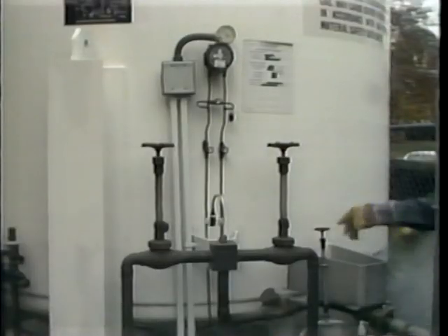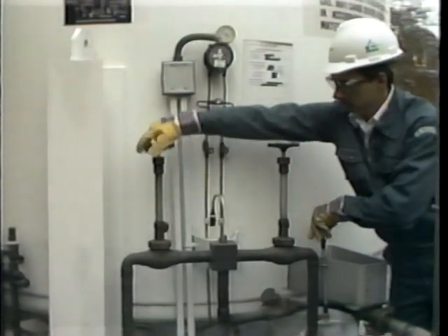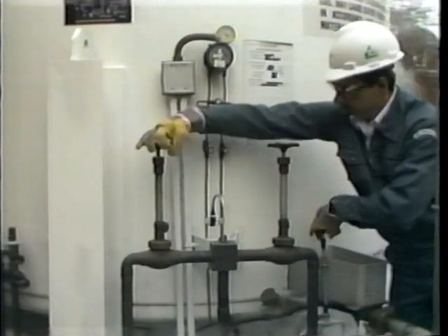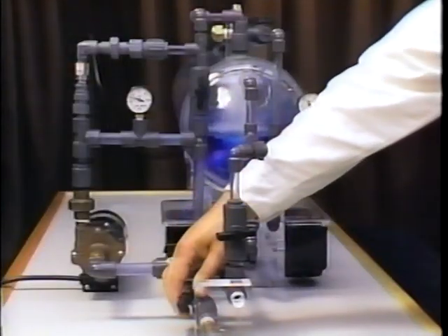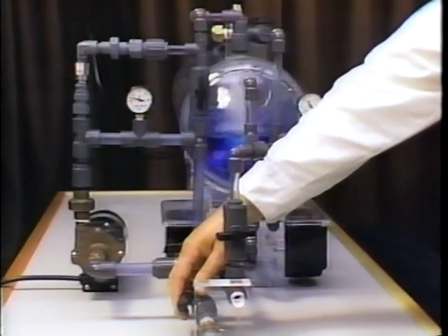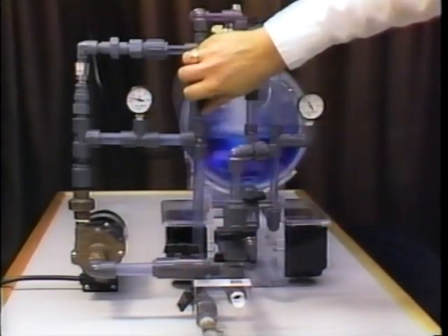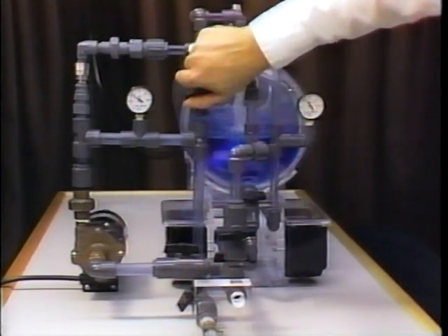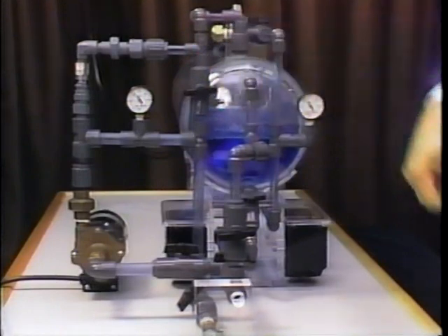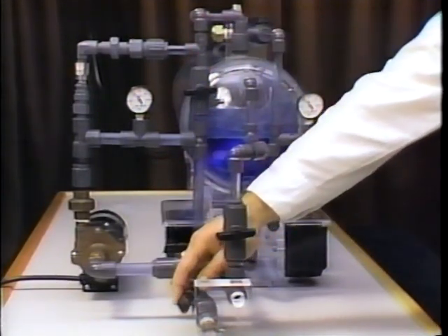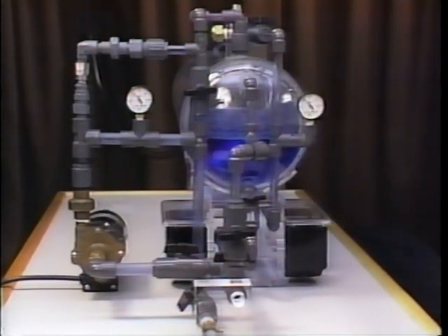The top fill valve is opened so that the tank can be filled in the non-vented mode. By opening the pump discharge valve and closing the pump recycle valve on the trailer, the pump discharge flow is directed toward the customer tank. As the level in the trailer begins to fall during transfer, it is extremely important to replace the volume of withdrawn liquid with vapors in order to maintain proper trailer pressure.